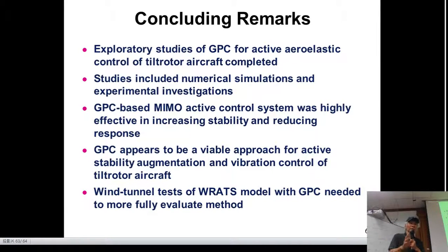If you use a computer to do the control, then you are talking about digital control. If you talk about digital control, then you are talking about something like predictive control. That's a pure digital control. All right? It involves system ID. You don't have to have a model by yourself. The data will give you a model, and that model will give you alpha and beta. And then from alpha beta, you will compute T, A, B. From T, A, B, you compute alpha C and beta C. From alpha C and beta C, you compute your control force.